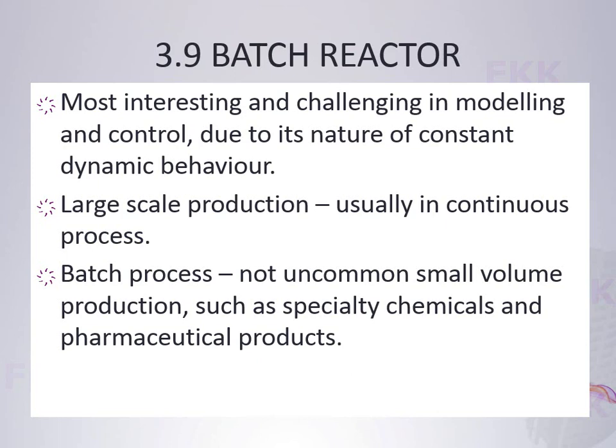Okay, and also if you were to process the polymerization process, it will take some time for the polymer to grow. So you cannot actually use the continuous reactor because it will go in and it will go out, then you don't have time for the polymerization to take place. So usually they put it in a batch reactor or a semi-continuous reactor, so that the residence time is going to be long, and it will take time for the polymerization process to occur until they reach the certain mass weight they want.